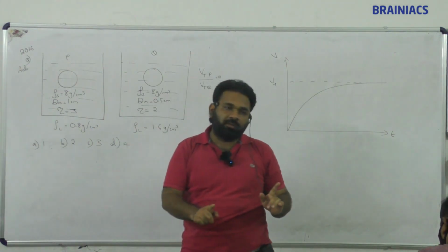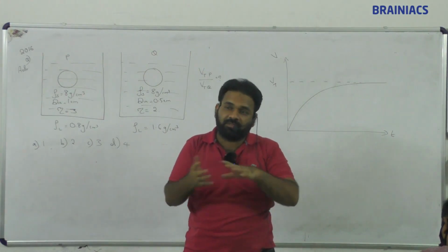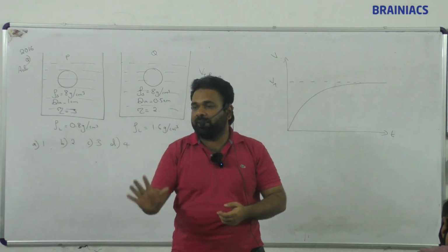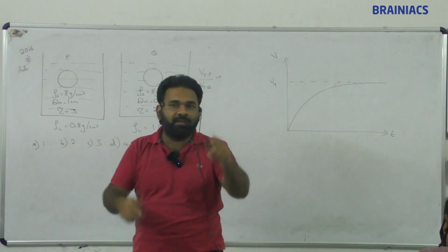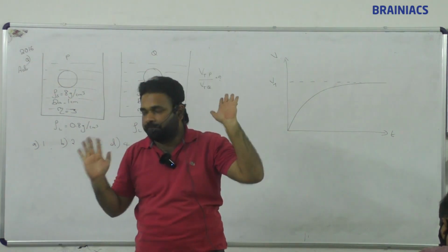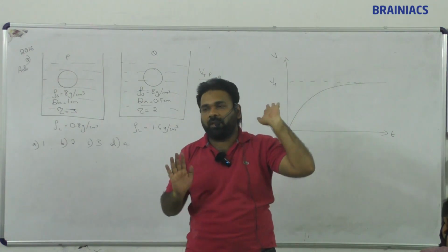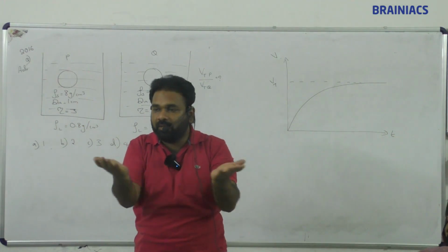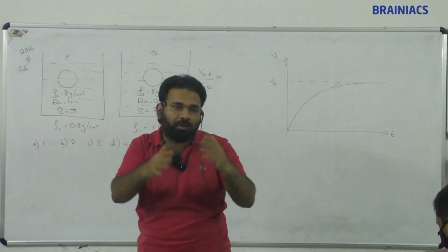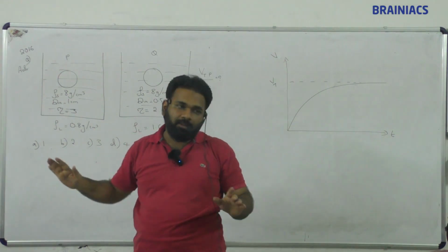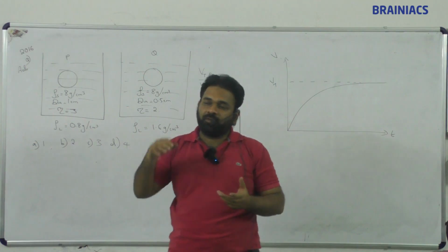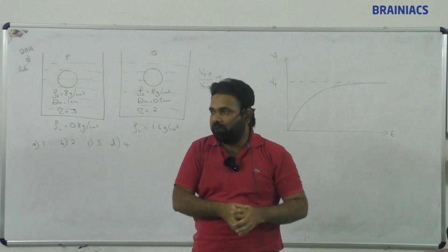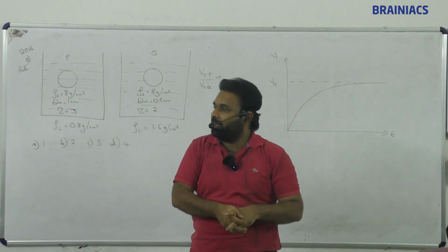Then what have we studied? Viscosity. So what is the viscosity formula? Viscous force F is equal to minus eta A dv by dz. dv by dz is the velocity gradient, change in velocity by change in distance. Then area is the area of the surface where the boat or any plank or any wood is in contact. Then what? If it is moving inside a fluid, then Stokes law. What is that formula? Force of viscosity 6 pi eta rv.